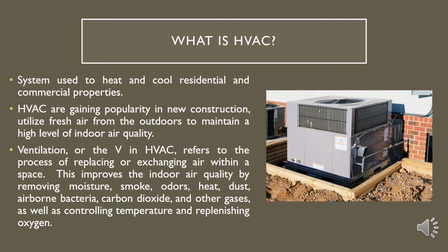of indoor air quality. Ventilation, or the V in HVAC, refers to the process of replacing or exchanging air within a space. This improves the indoor air quality by removing moisture, smoke, odor, heat, dust, airborne bacteria, carbon dioxide and other gases, as well as controlling temperature and replenishing oxygen.